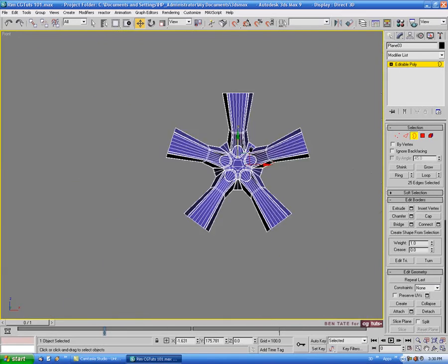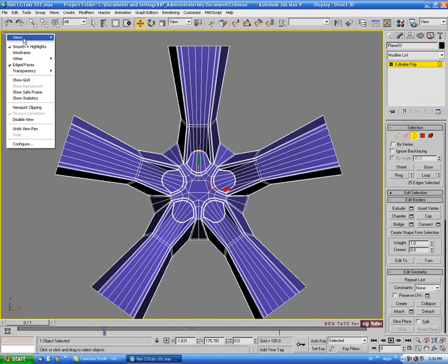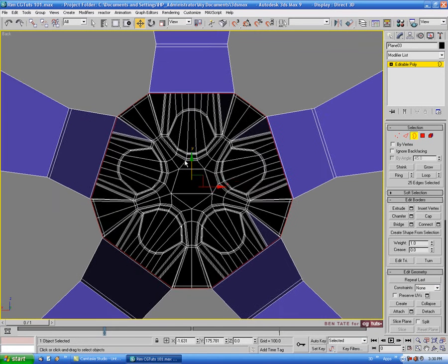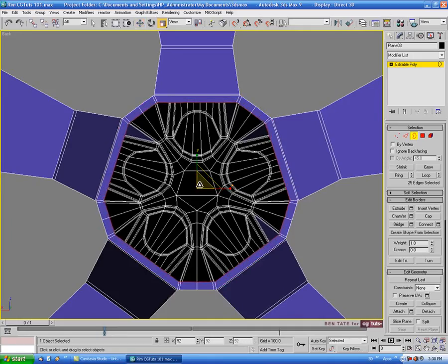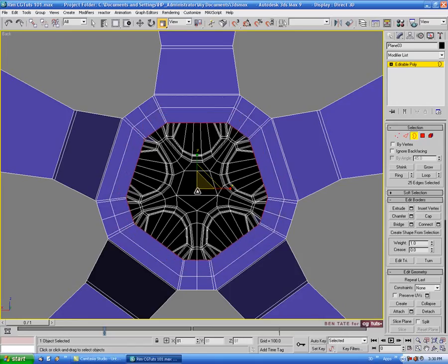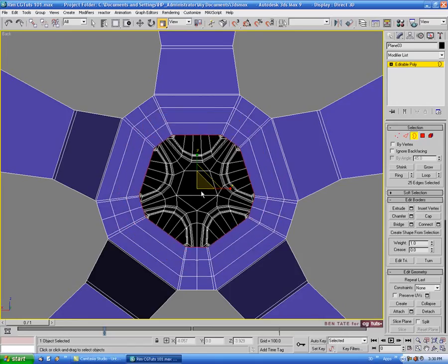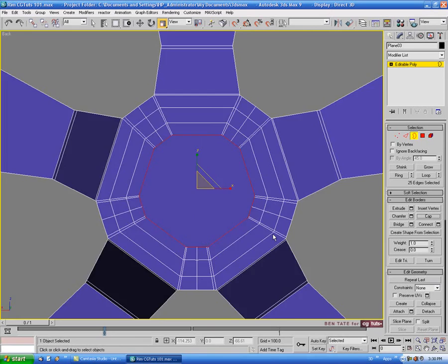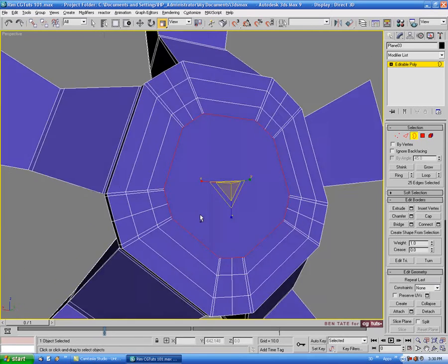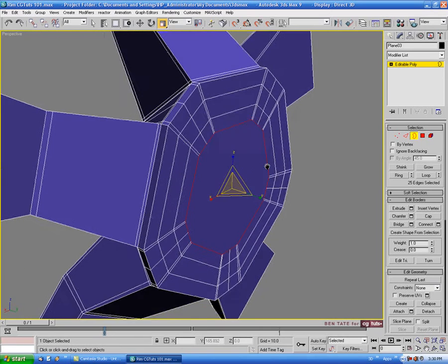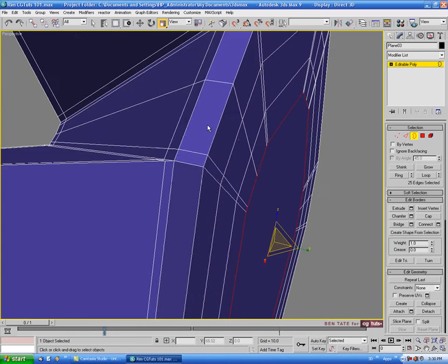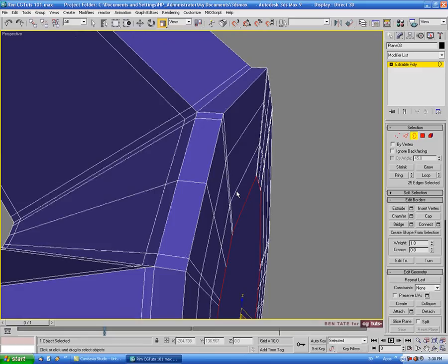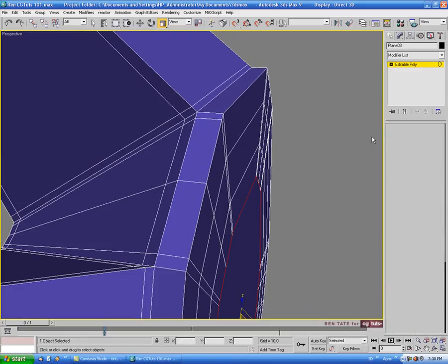Then we'll go into the front view. Let's just actually change this to the back view. Alright, and with the border still selected, I'm just going to go to the scale tool, and I'm going to hold shift, and we're just going to scale this in a few times. Let's do 3, say, and then we'll just hit cap, and then I'll close that up. And that really shouldn't give us any problems, even though it's a giant n-gon. So let's go on the side here, and let's add a support.